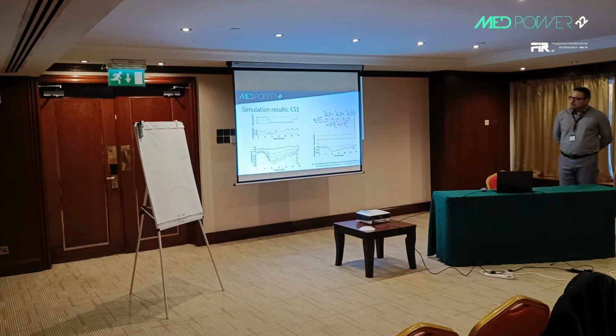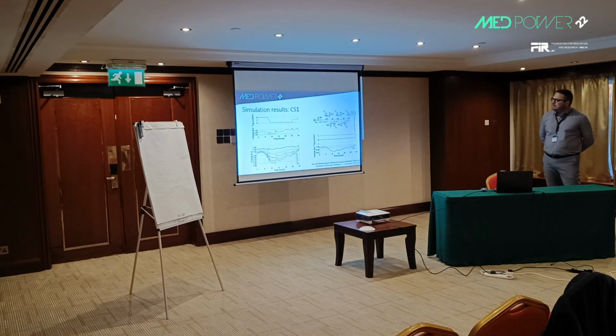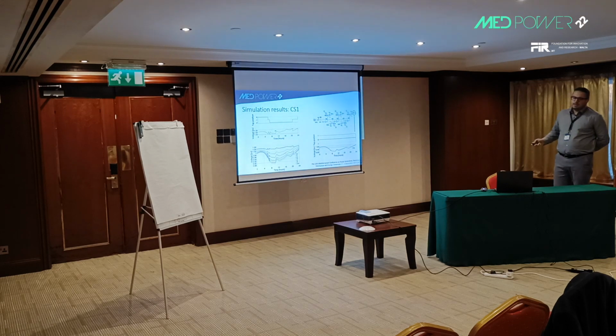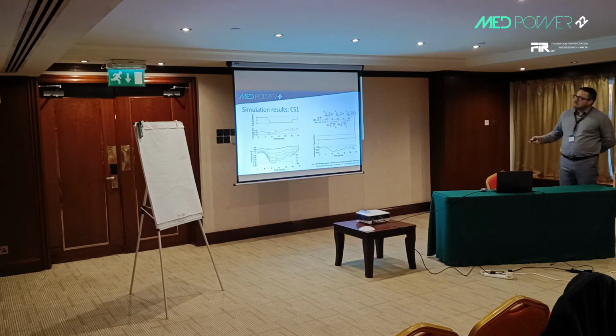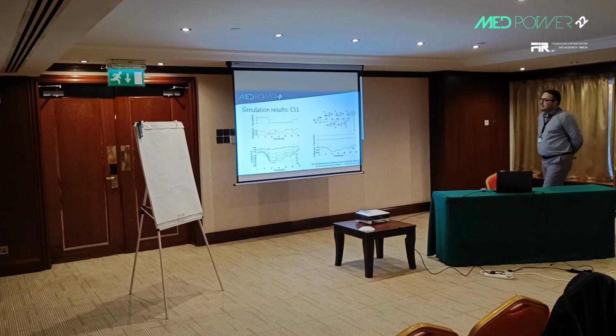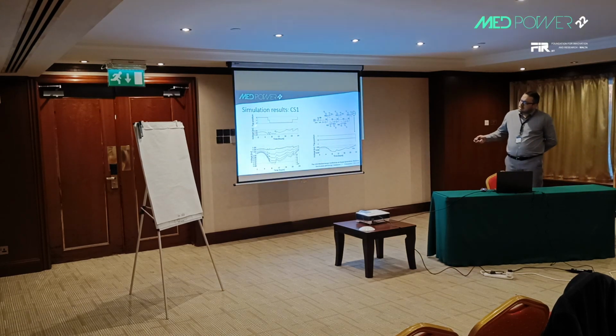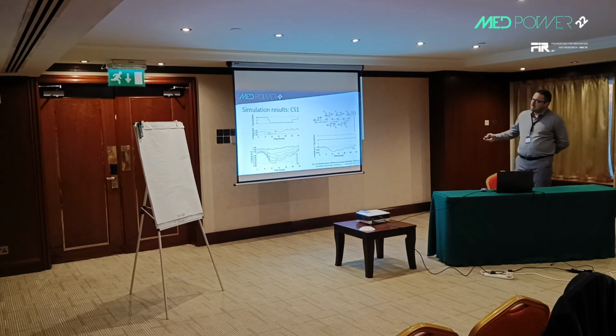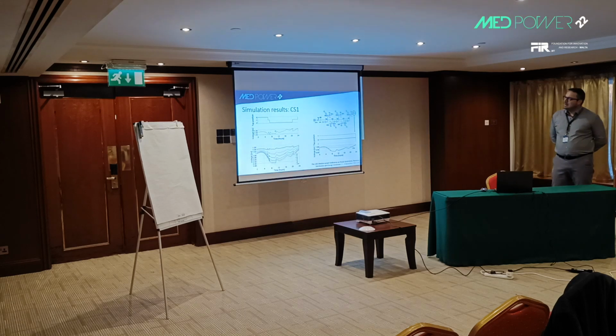The base case, which is case study 1, is the case where only the main transformer regulates the voltage. As we can see in the first figure on the top of the slide, the tap changes on this transformer are sufficient to keep the voltage in the secondary bus within the deadband.